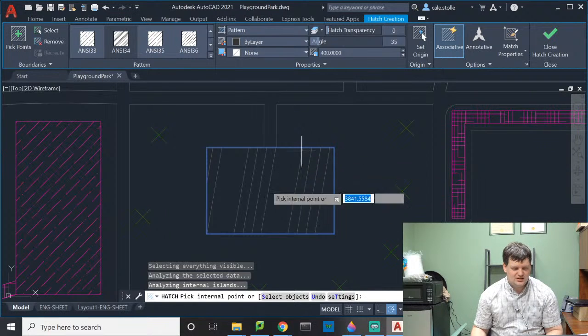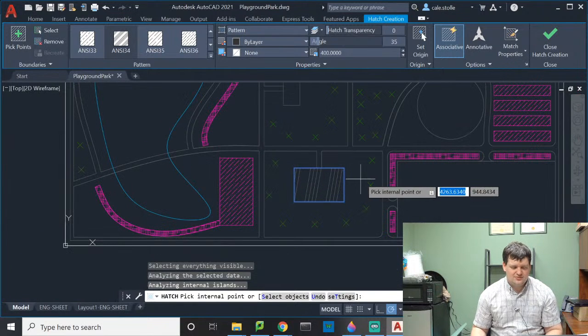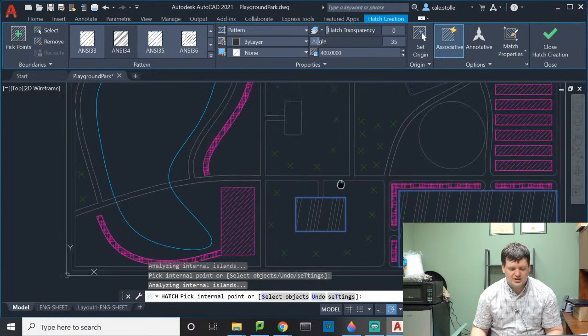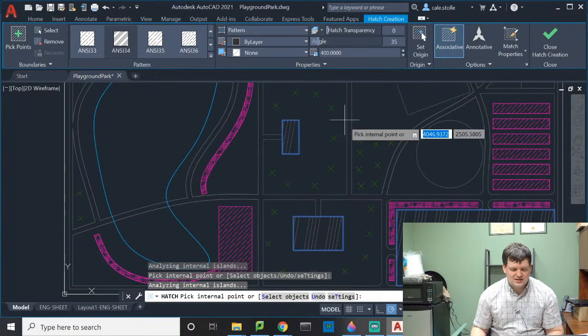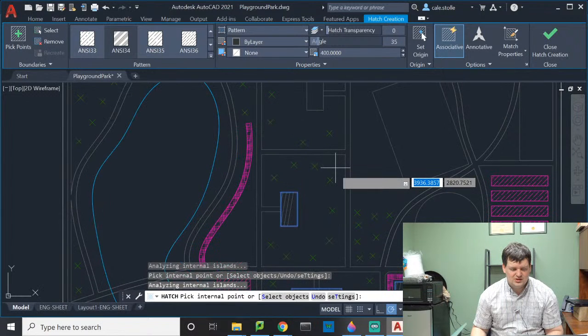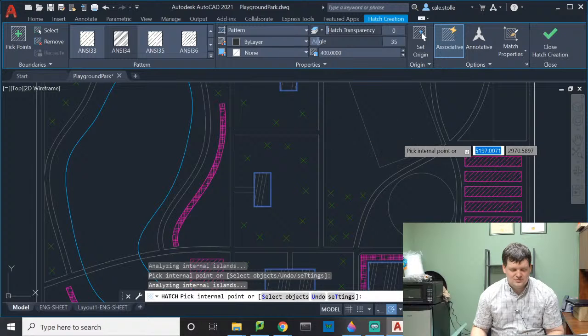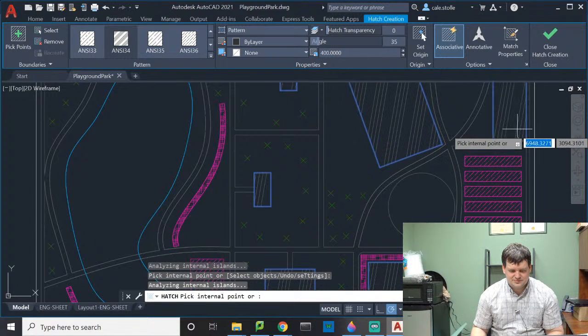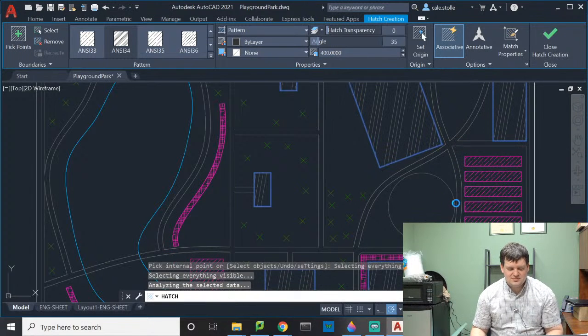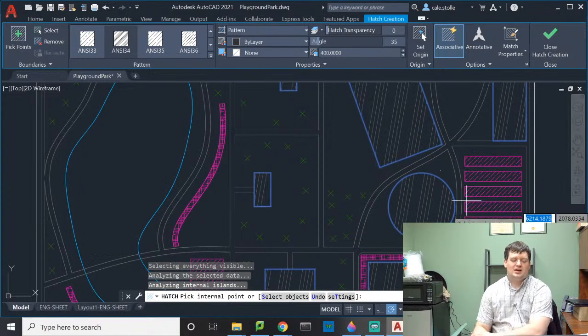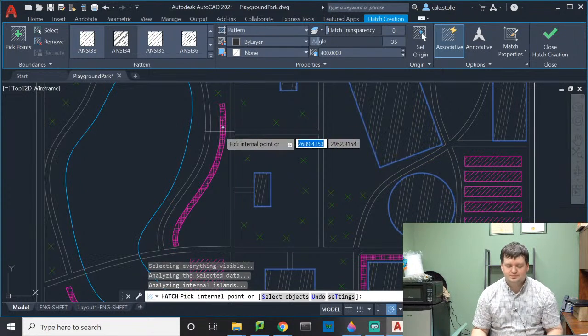And you'll notice if I click here, okay, 400 is a little bit too big of a scale, but I'll go ahead and put in all of my pavements, and I'll have them all be at the same angle, the same format. Okay, for each of these, I'm going to go ahead and pave them and make them 7 inches deep.